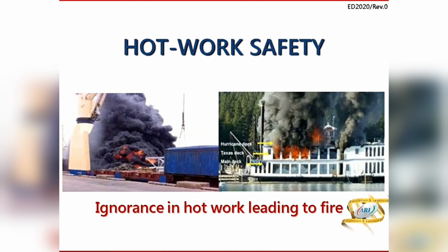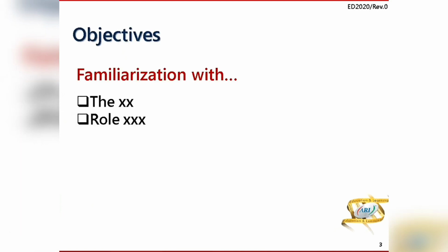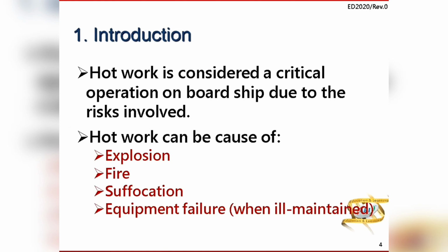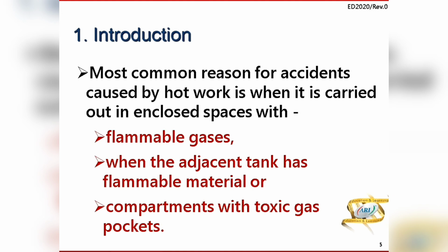Now, hot work can lead to a fire, which you can see here. So it is considered critical for operation on board due to the risk involved. It can be a cause of explosion, fire, suffocation, equipment failure. The most common reason for accidents caused by hot work is when it is carried out in enclosed spaces, because you have flammable gases there, or the adjacent tank has flammable material, or the component itself will have toxic gases in the various pockets.